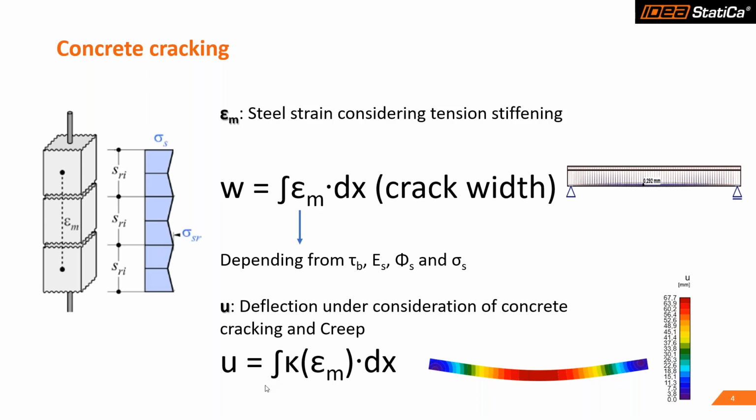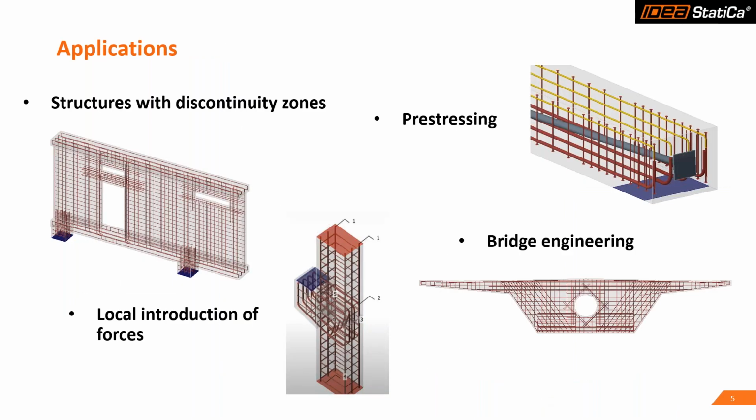So the program integrates numerically the curvature, and then we get the deflection under consideration of concrete cracking. Creep is also considered, and of course, as said, all the non-linearities. So application, where can I use this program?